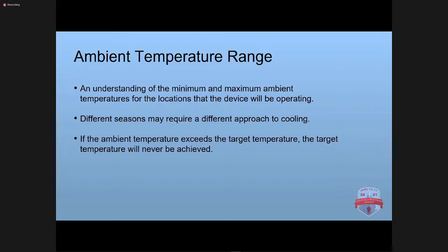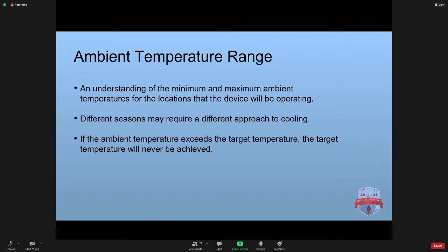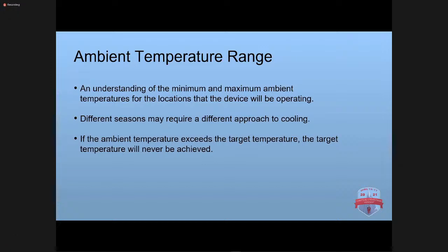And this comment basically is describing that if the ambient temperature is lower than what your target temperature is, or where you want to lower your equipment to, there's no way that's going to happen, because you're introducing that ambient into your environment, into your enclosure, to attempt to cool it. So clearly, if it's higher, it's only going to raise the temperature. If it's the same, it would maintain. So just be smart with where you want to run.